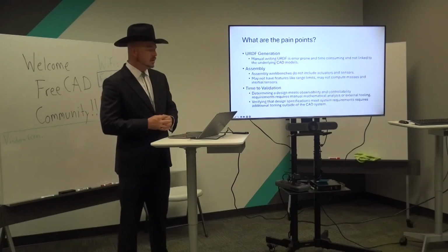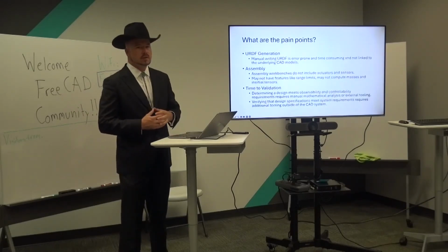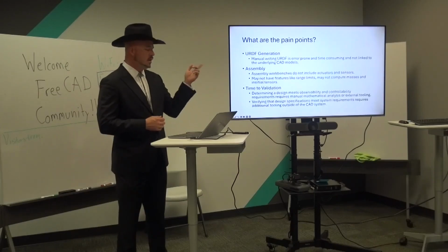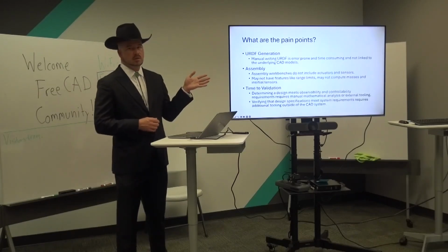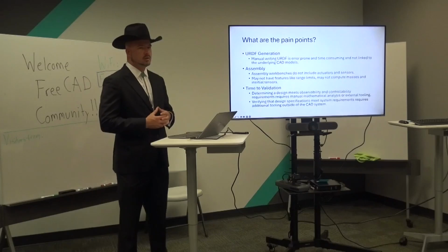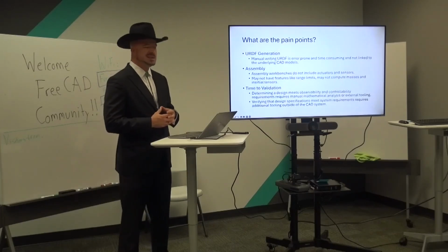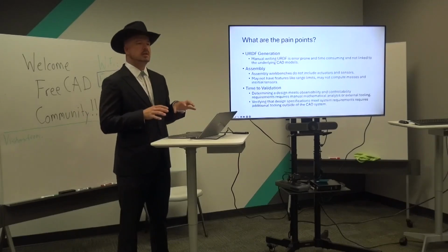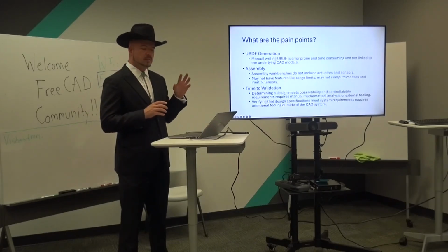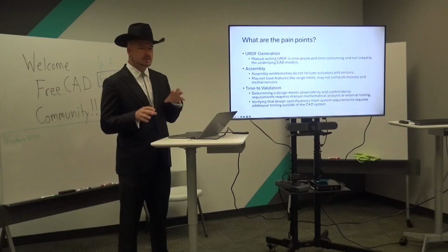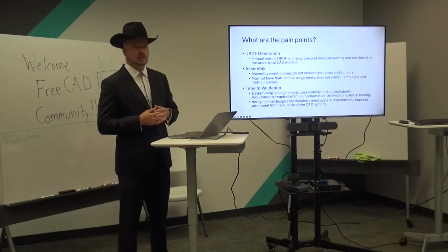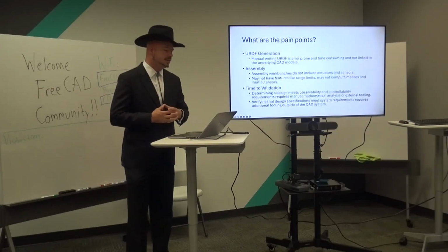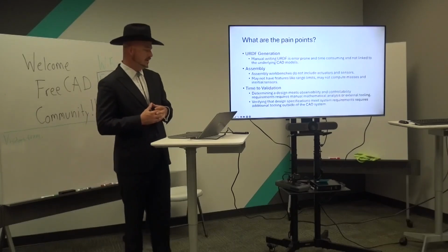So what are the pain points? Well, we've already seen one, the URDF generation. Manually writing these URDF files is a real error-prone and time-consuming process. And it's not linked to the underlying CAD model. So if we change that CAD model, we have to then modify our URDF files. And if those fall out of sync, we may end up with some surprises that we don't want.